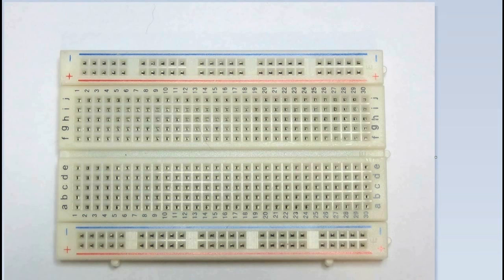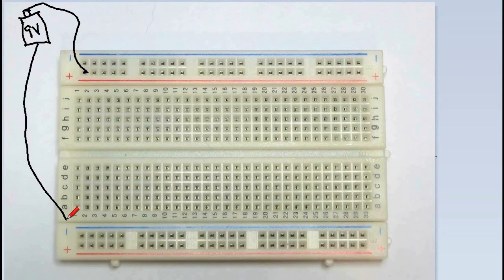Open half breadboard. Okay. So now let's say we have a 9-volt battery. This gets a little more complex. So this is 9-volt, and we plug our positive side into the positive rail, and our negative side into the negative rail. And when we get into diodes, we're actually going to add something in here. It's actually going to be protection for our circuit, so that if we accidentally put something in reverse, we don't blow it up.